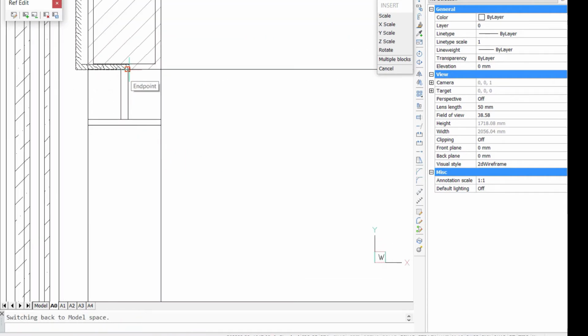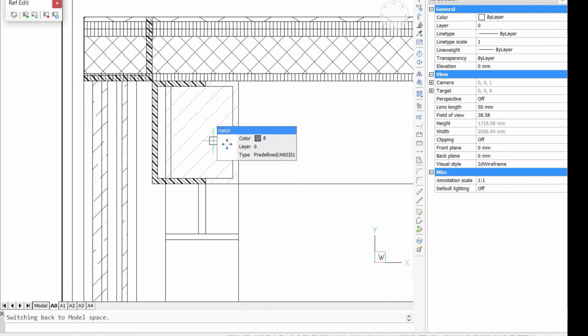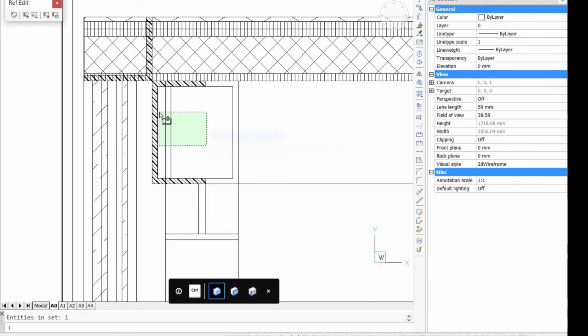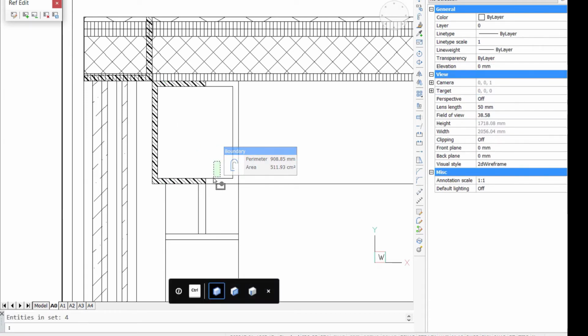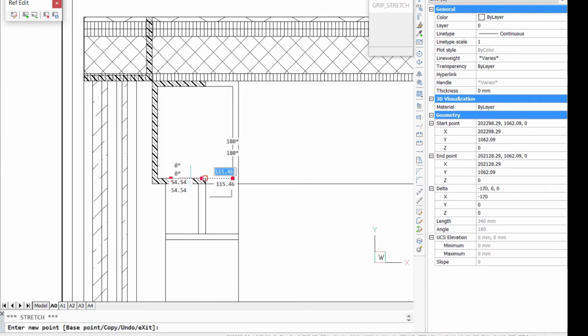The first block is for the steel channel that is spanning between the tube steel columns and the steel angle on the exterior, which provides the boundary for the glazing assembly and the roof. We'll explode the block in case we want to edit it further, and we'll delete some hatches and lines that were part of the generated BIM section, so that it is represented correctly.